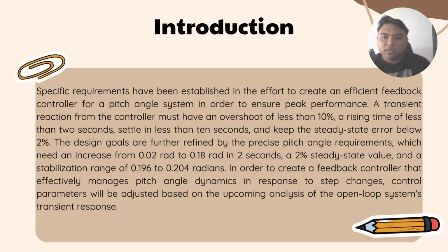So, for my part is introduction. Specific requirements have been established in an effort to create efficient control for a pitch angle system in order to ensure peak performance. The reaction from the controller must have overshoot less than 10%, a rising time less than 2 seconds, and settle in less than 10 seconds for the settling time, and keep the steady-state error below 2%.